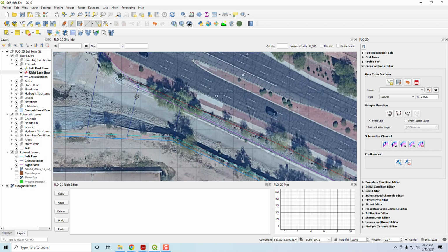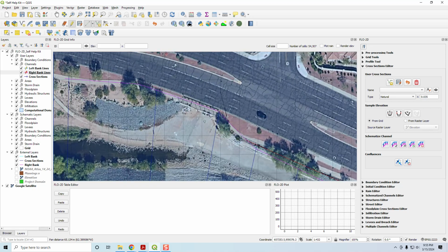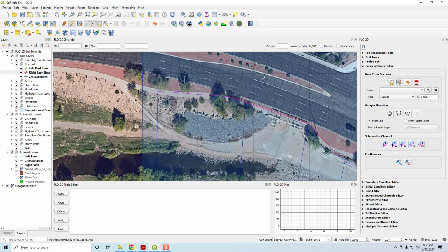And then, I guess that's fine. And then just be careful around this culvert to make sure that you're up on the top of that elevation of that culvert. And it looks like, again, I've pulled that all the way out to this last spot right here. Right click, OK, and save.